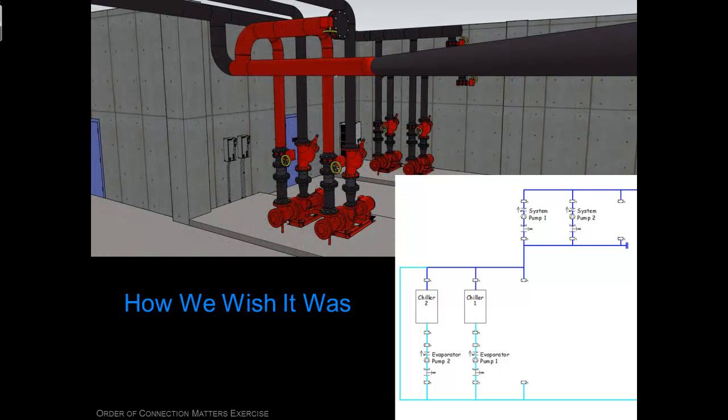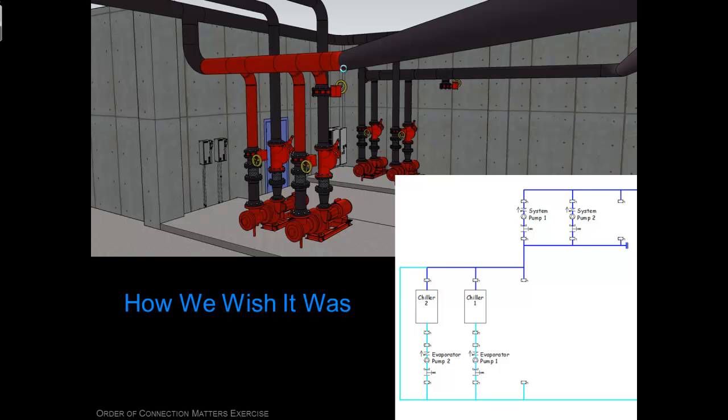See, before, you tee up, you come back and drop to the pumps. Now, the first pump comes right off the return as it goes into the plant. The second pump comes right off the return as it goes into the plant. There's that capped valve for future, and the bypass goes this way.